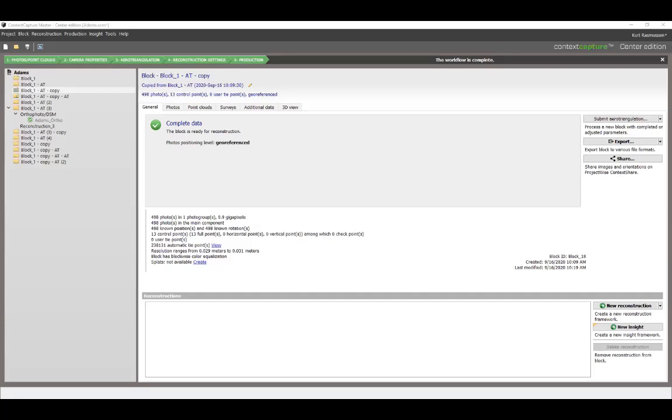Now, when I get into more accuracy, what I say to users, and it is what we back up, is we're accurate to 2-pixel resolution. So that's from the photogrammetry aspect of it, but that has nothing to do with the ground control. That's you guys out in the field. And like you said, it has to do with vertical. If you have control at the bottom of a hill and the top of a hill, that's better than having them spaced horizontally out, but vertically they're on the same plane, and those kind of things. So there is a lot that comes into setting your control and the accuracies, but I do have a document.